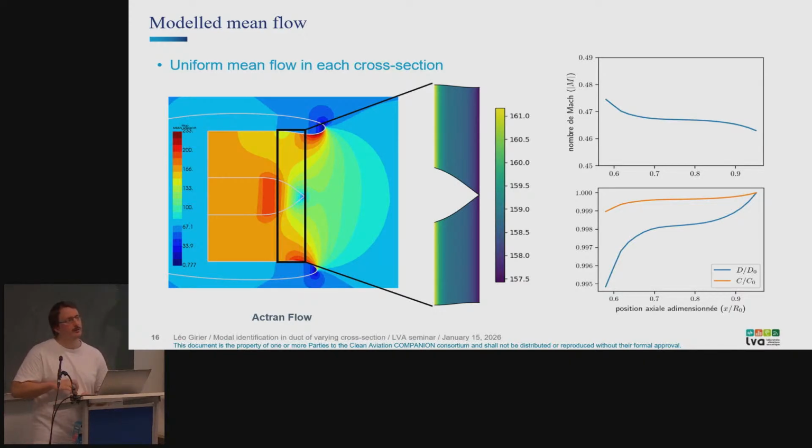This is not convection, no. The acoustic waves propagate, and the wavelength that they have is compressed by the mean flow if they propagate against the flow, or extended if they propagate in the direction of the mean flow. That's a Doppler effect. Convection is the fact that a quantity is convected by the mean flow. This is another effect.